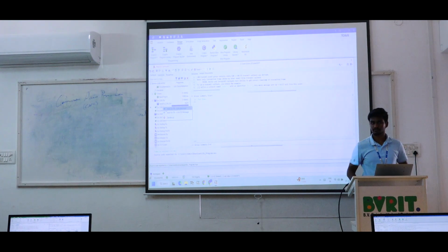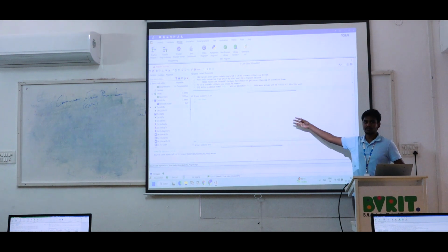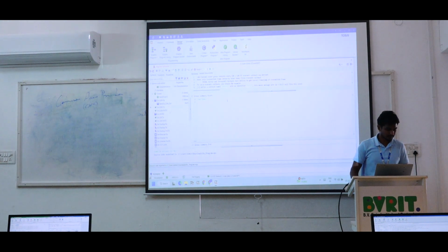Right click. Stop the simulation, stop the scripting. The major point here is that before editing we need to stop the script, and before starting the script we need to compile the source. These two are major key points.